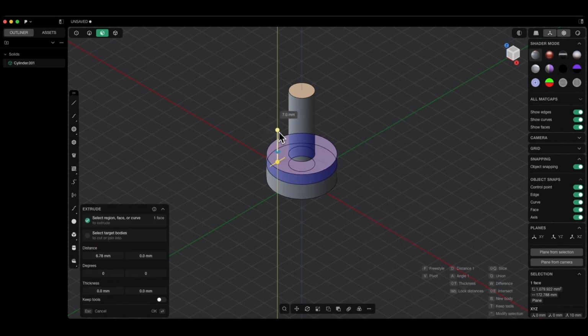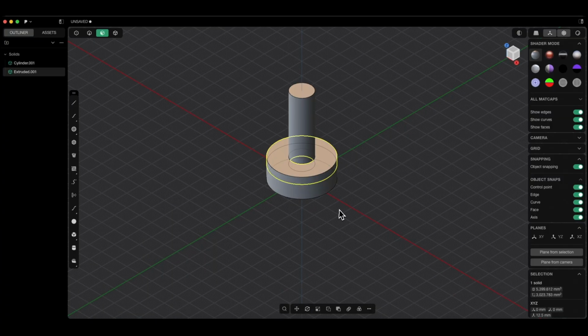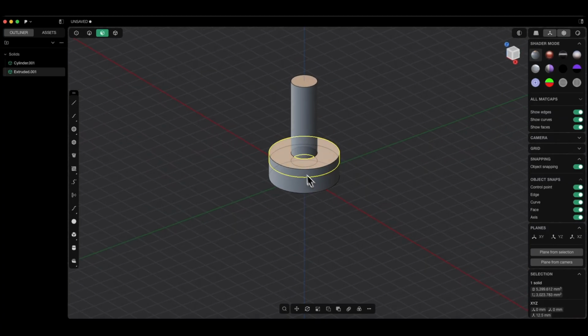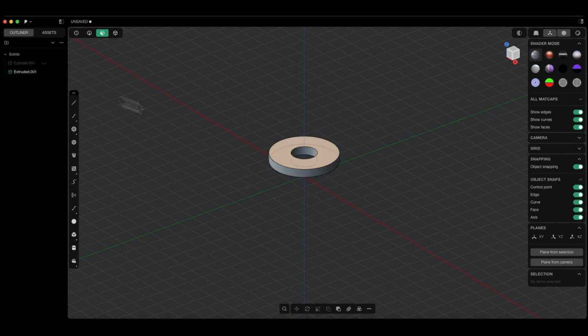And if we add an extrusion, we can either extend the solid or create a new one. First, I'll set the extrusion height, press D, then type 5, and then press enter to confirm the height. And now press B to make it a new solid. And click OK, and we've created a new solid from a face of another solid. Now I'll hide the larger cylinder.